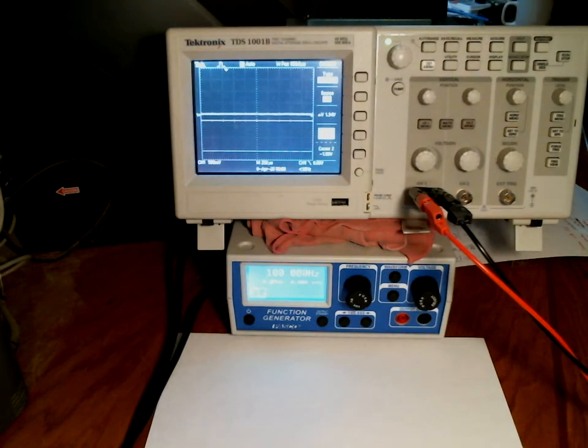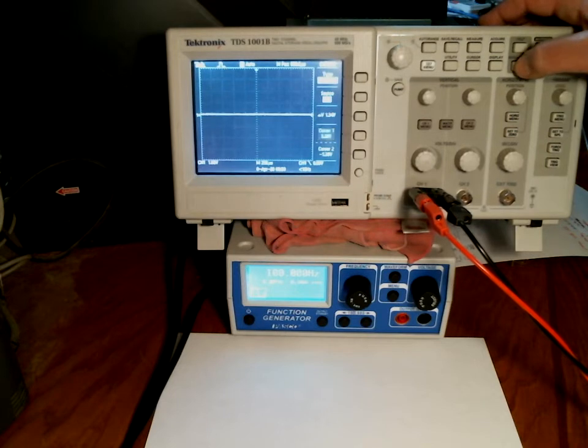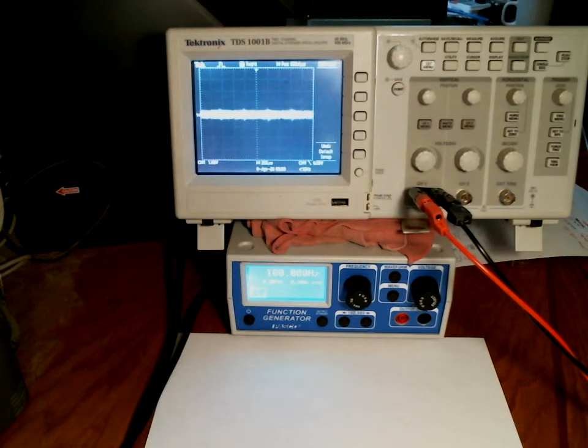To see this RC time constant and decay, we're going to use this oscilloscope. And this is a nice modern digital oscilloscope. One of the really good features on these things that you should use is it has a default setup button, which I'm going to use. The idea there is that after it does the default setup, then you know that there's no weird thing that's been selected on this scope by the previous person using it that would persist after you turn it back on. So it gives you a known good state.